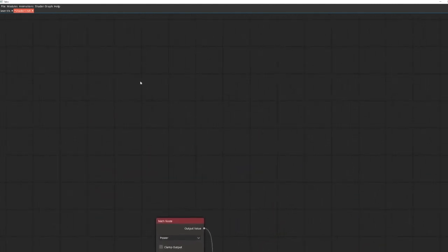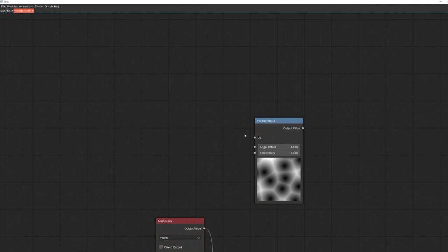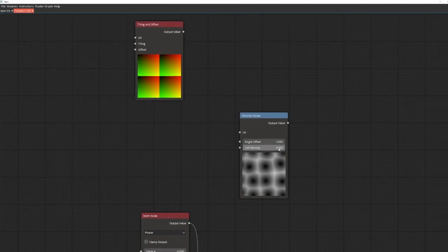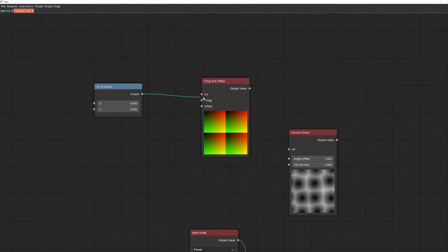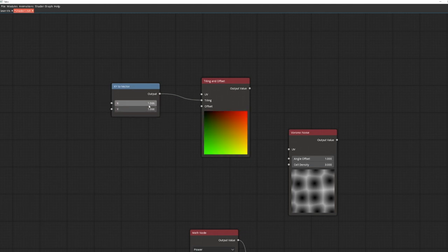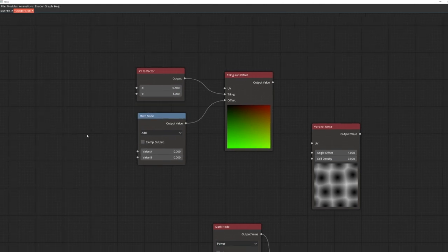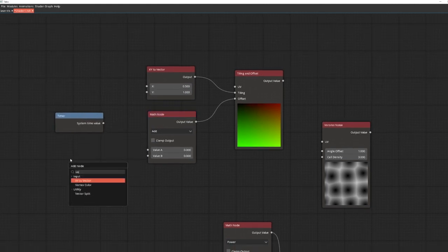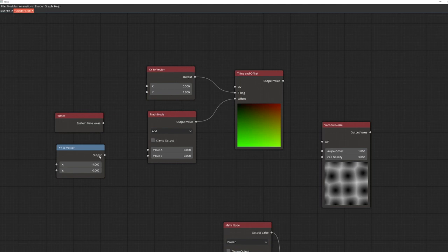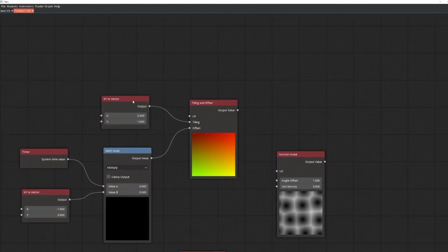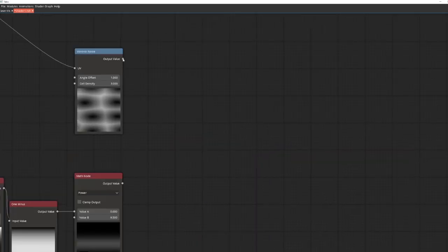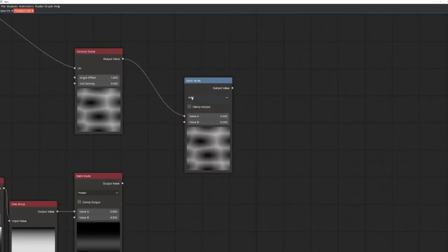At the top, I will make another element for the laser shader, which is its distortion animation. For that, we'll use Voronoi noise, and that will just tile and move to the left using time. Multiplying our two parts will give us the animation we're looking for.